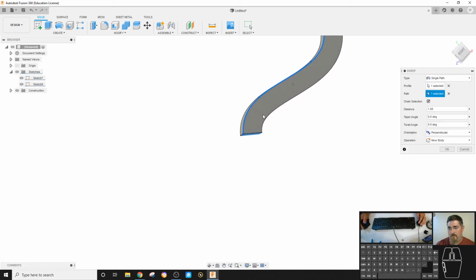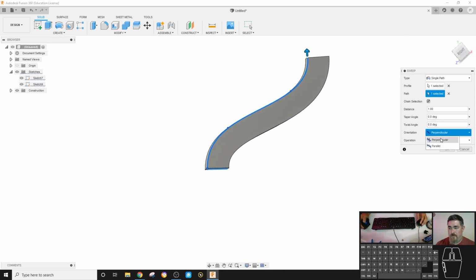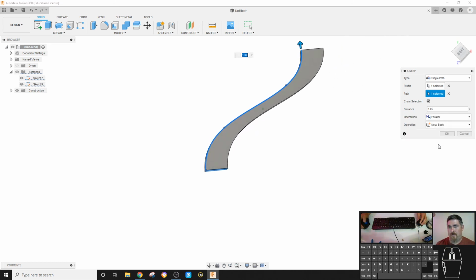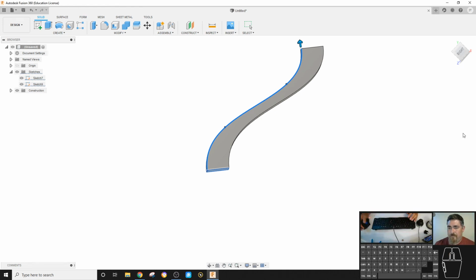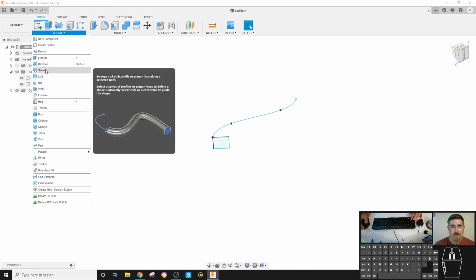that, now you can see that it doesn't have that weird hiccup here that the one at the beginning of the video did, because now it's actually following that. And then here's that parallel option also. You can kind of see it better because now it's perpendicular the whole way. It wasn't already at some weird angle to it. So that's the sweep command. So try it out.